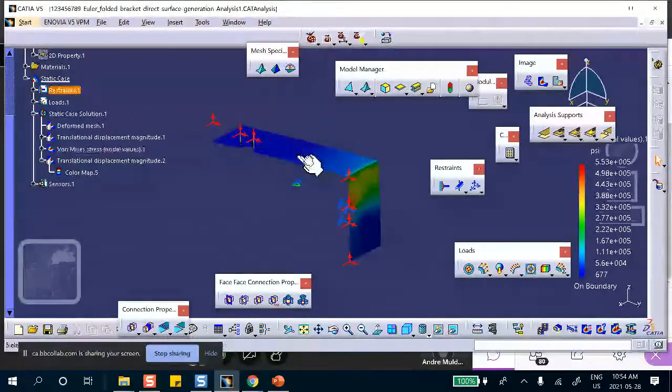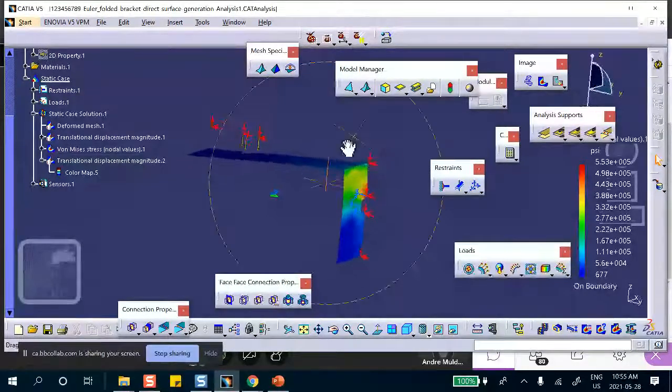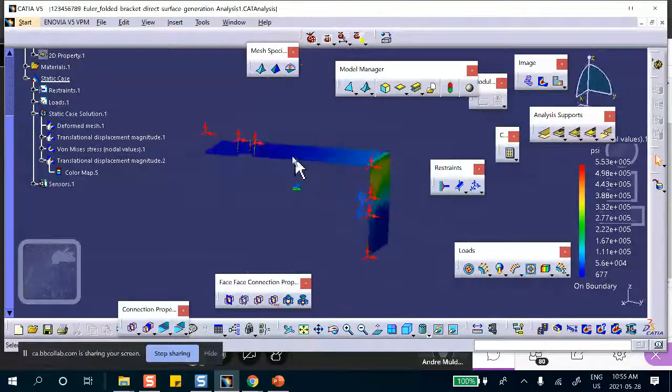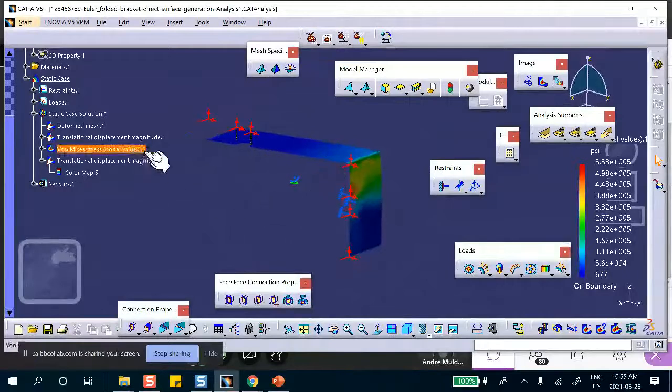Basically, give it more stiffness. That's what the bracket really does. The stiffener here, like right there, something like that, will give you stiffness so that it won't deflect as much. The other option is to make this thing thicker, right? So let's go ahead and make it thicker, no problem.